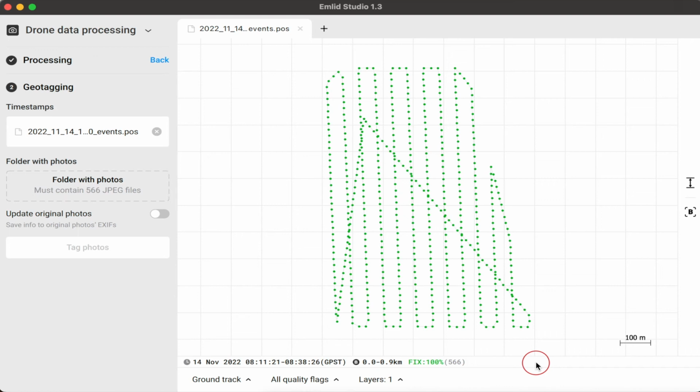And single means that the rover has found a solution relying on its own receiver and base correction is not applied there. And precision in standalone mode is usually at the several meter level, which you don't want, which is a big no for any kind of post processing. Okay, so that is single.